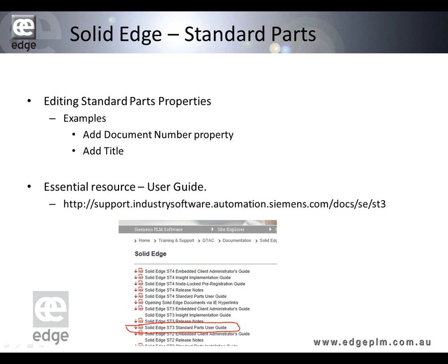I see some questions coming up. You know, I can only get 6 and 12mm. Yes, I'll explain it. The reason is that you haven't added the rest of the libraries. You haven't added the machinery library, and you haven't registered that library. Once you register that library, you'll get a bigger set. You may have thought you'd installed it, but it still needs to be registered. That was on my earlier slide.